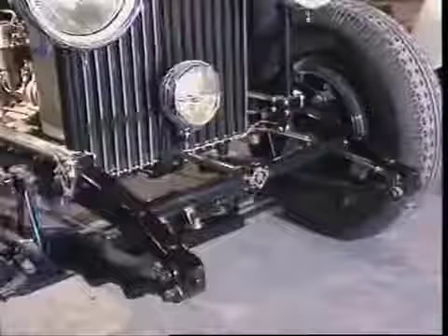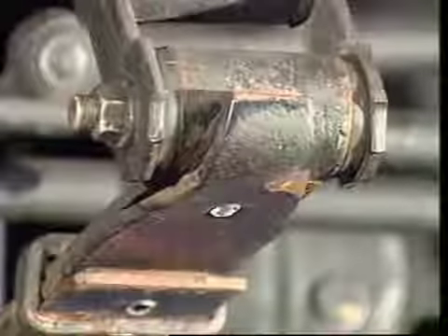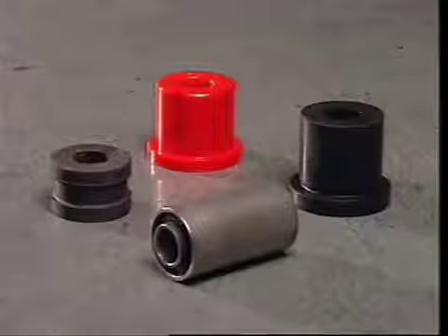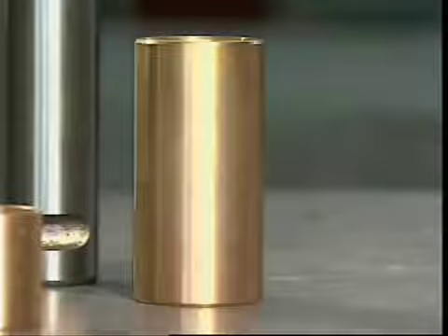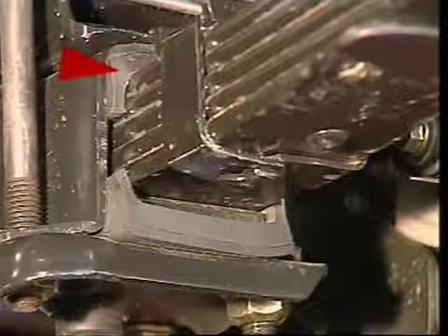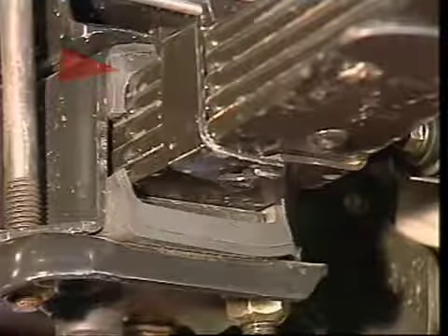Some springs have inserts between the leaves of plastic, nylon or rubber. They act as insulators to reduce noise transfer and friction as the leaves move under load. Some older vehicles completely enclose the leaf springs in grease. The spring eyes are fitted with bushes, usually with a rubber, flexible section. But nylon and urethane bushes are also used, and sometimes bronze for heavy-duty applications. Rubber insulating pads between the spring mounting pad and the spring also act as insulators. And similarly, between the spring plate and the spring.